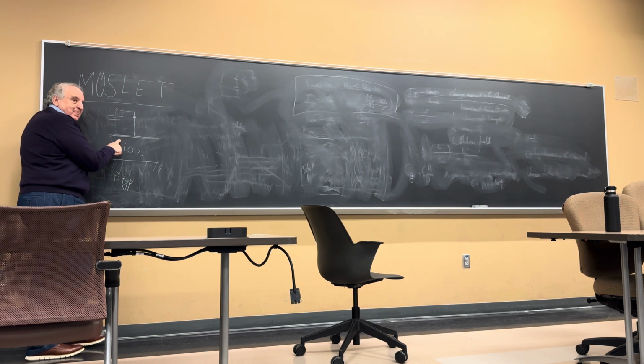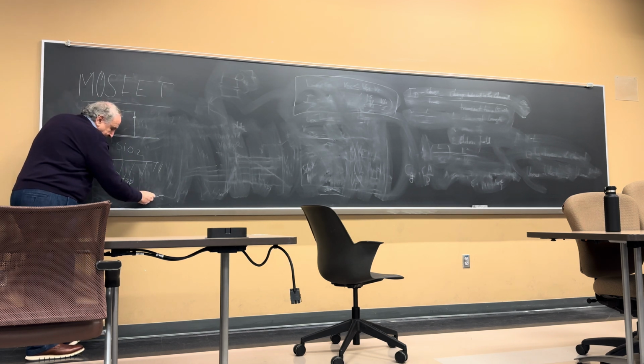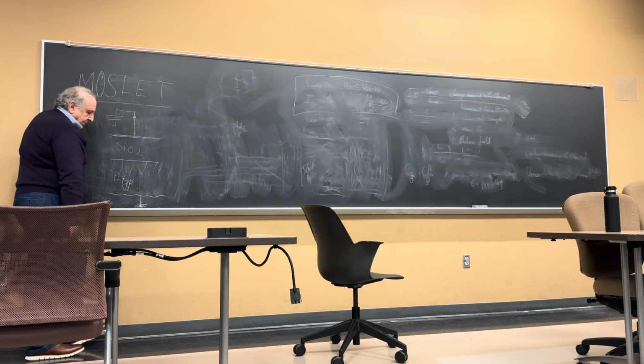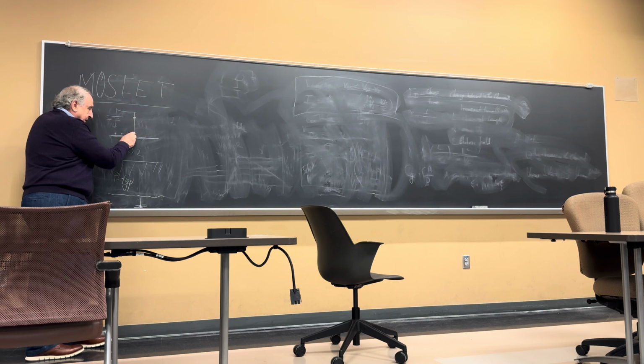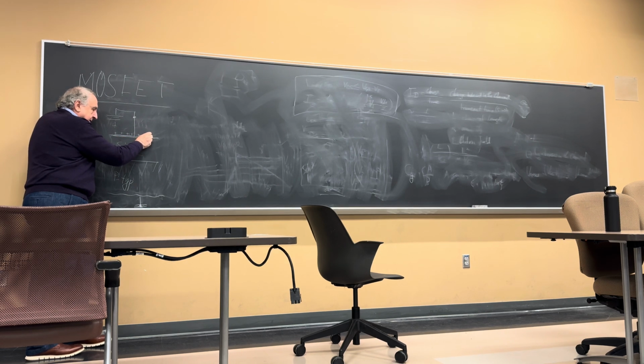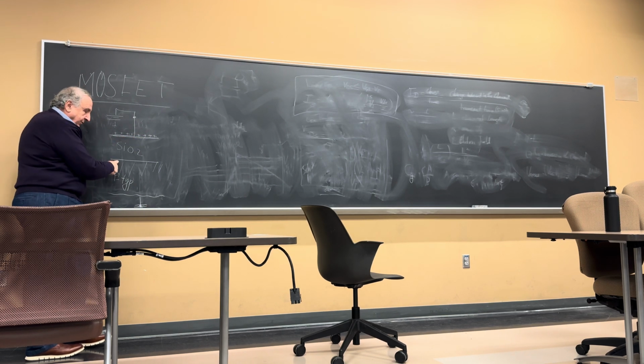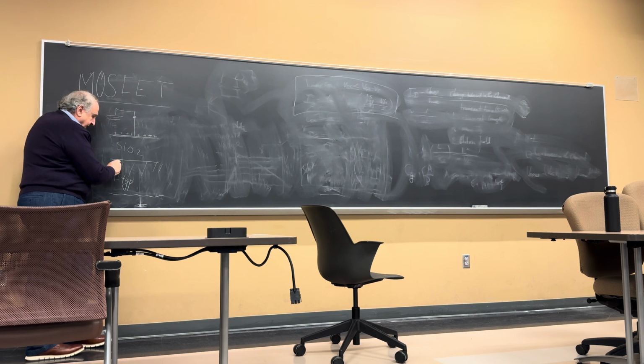What happens on this plate of a capacitor? This is a capacitor, right? Yes. This is P-type, and right here there's a connection. Say I ground this connection. All right? What happens on this plate? If I put positive voltage there, you get positive accumulation of charge here, right? What do you get on this side? Negative. Where does the negative come from?